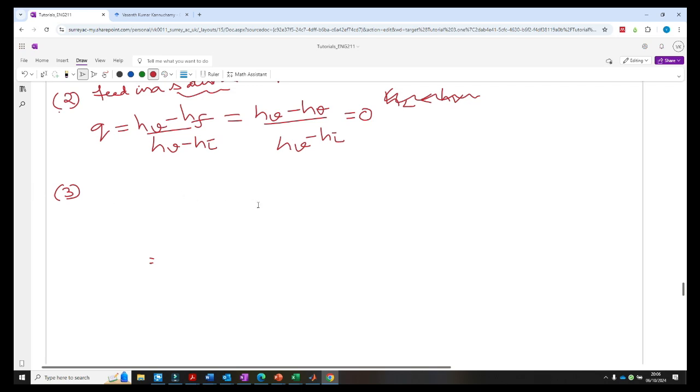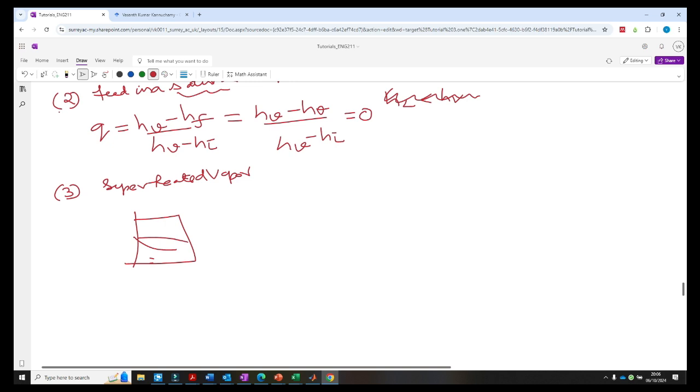So depending on the Q, we are going to determine the slope of something called the feed operating line. We will come to that later, not now. Okay, let's go to the next point. Maybe superheated vapor. This is easier to answer. Superheated vapor, so what is that? In the TXY diagram, superheated vapor is somewhere here, and this is greater than HV. HV is your saturated vapor, which is somewhere on this side of the tie line. So definitely superheated vapor.